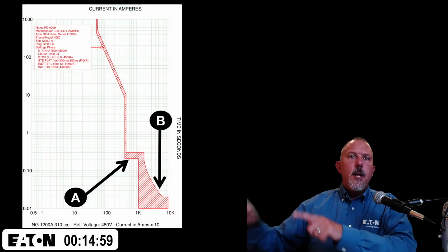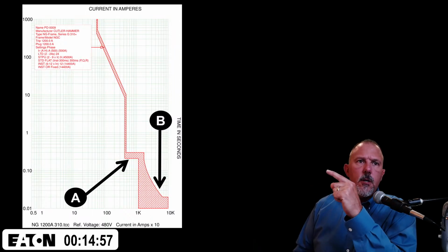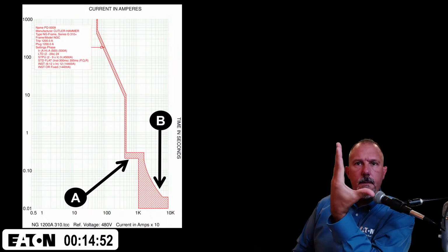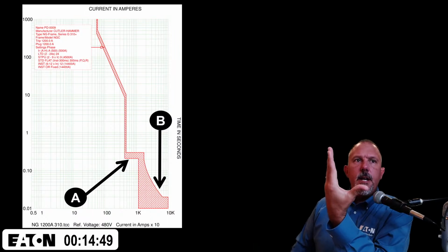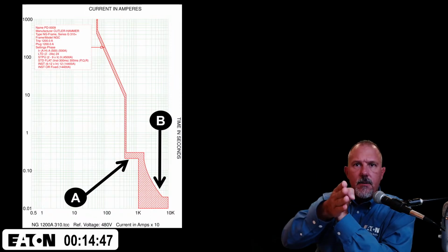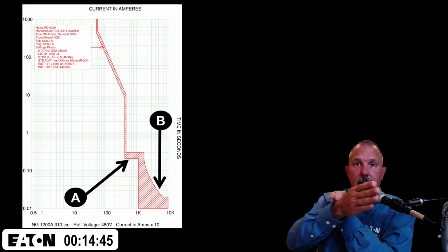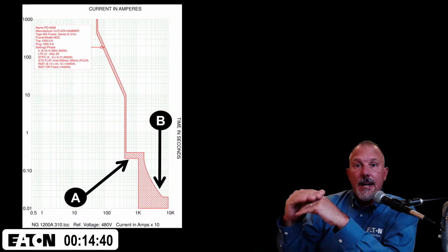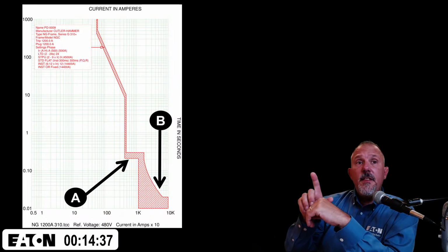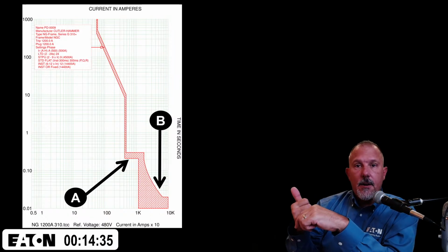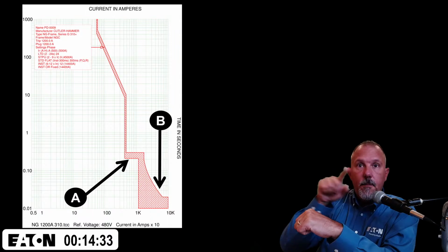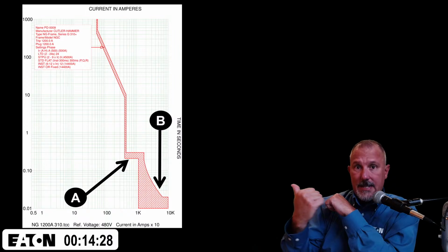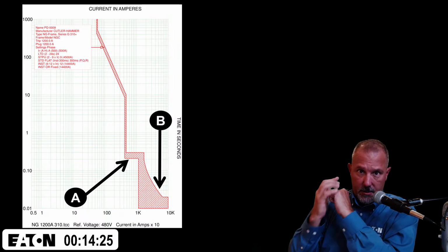Boom. All right, so in this picture, you see that knee, which is this way, right? So I have the breaker curve that comes down and then over this way. That knee, if this was a power circuit breaker, that would be a short time delay. The interrupting rating could be much higher. In some cases, that elbow does not come down to 0.01 seconds. It goes all the way out to the interrupting rating of that circuit breaker.